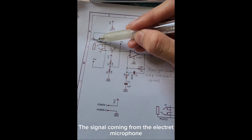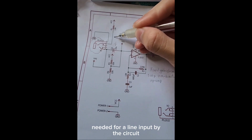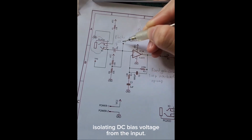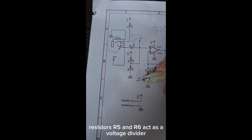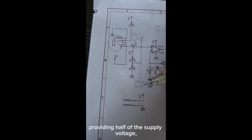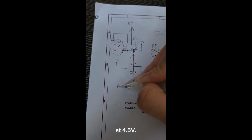The signal coming from the electric microphone needs to be brought up to a certain level needed for the line input by the circuit. Capacitor C1 acts as a coupling capacitor at 10 microfarads, isolating DC voltage bias from the input. Below this in the schematic, resistors R5 and R6 act as a voltage divider with 10 kΩ each, providing half of the supply voltage, which will supply the op-amp to work in single supply mode at 4.5 volts.